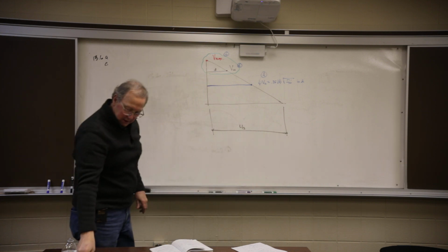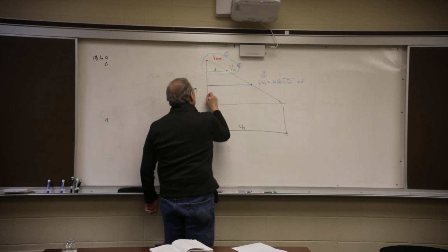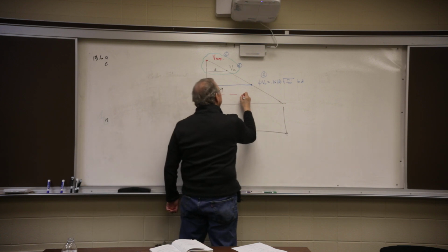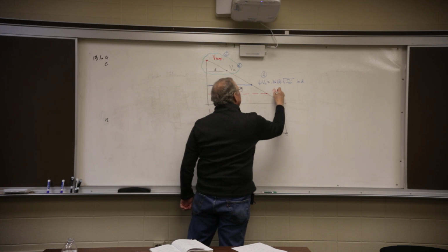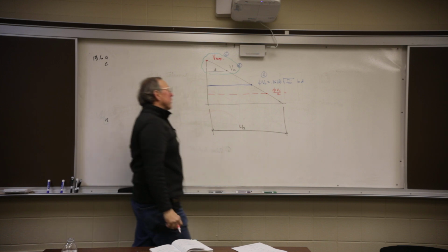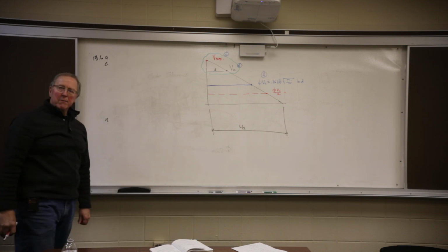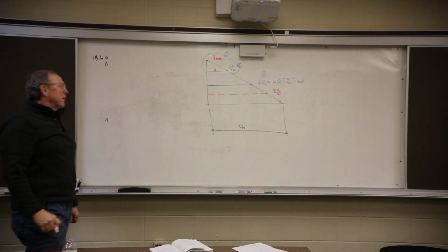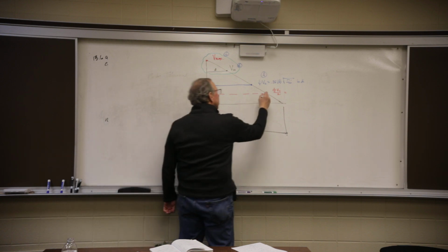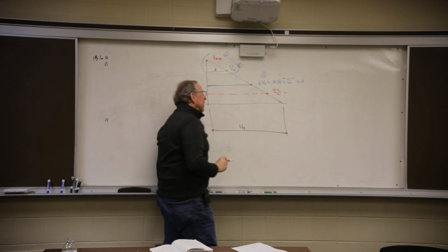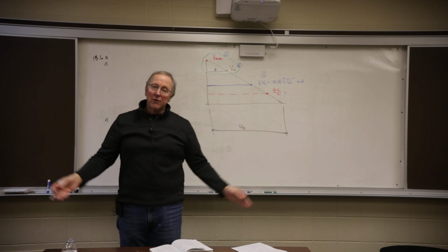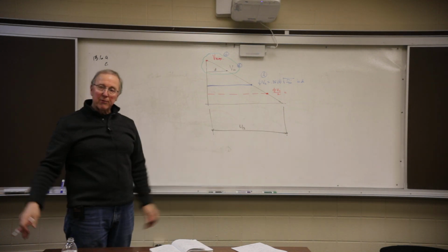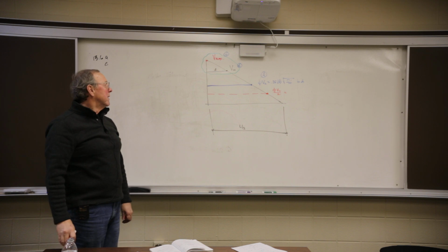The dashed line comes right across here, and it has phi VC over 2. So if I calculate the top one, I divide it by 2, I end up with a point on my slope. And hopefully everybody realizes the slope of this line is the application of the load rate: 2 kips per foot, 6 kips per foot, whatever it might be.